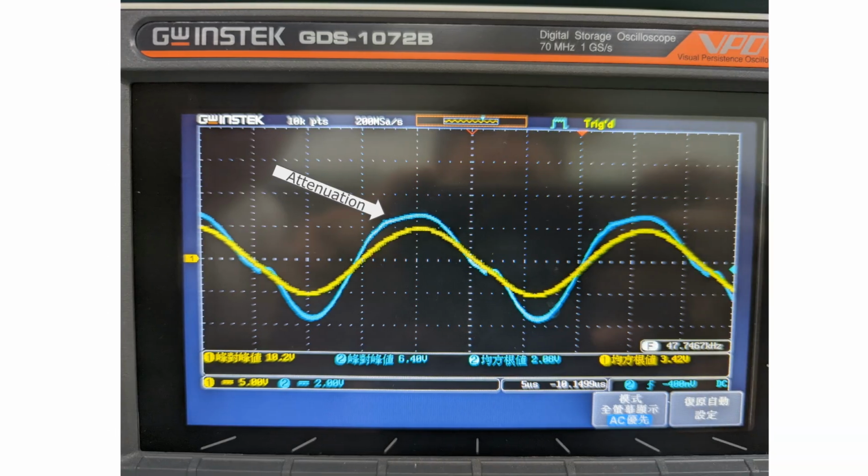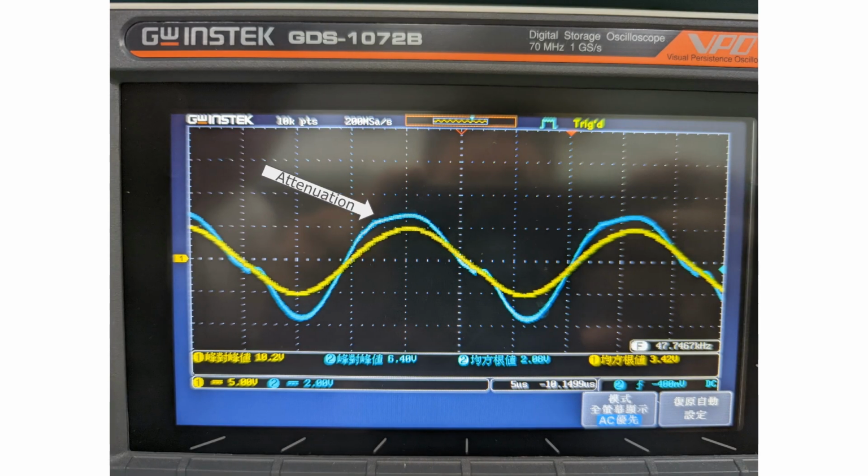Then high frequency above the cutoff. The oscilloscope image clearly shows significant amplitude attenuation and a phase shift approaching -90 degrees. But notice at high frequencies, there's often noise in the signal, which can cause some discrepancies between theory and practice. High frequencies are blocked, as expected from a low-pass filter.